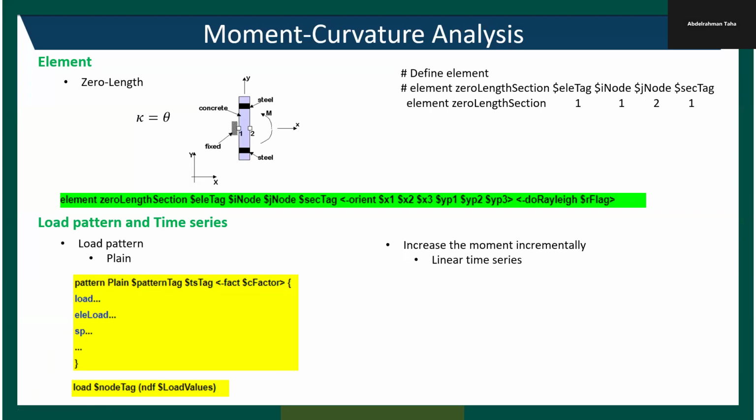Displacement control is basically you specify the displacement or deformation that you want the cross section to undergo, and then record the corresponding stress or corresponding loads to this applied displacement or deformation. So basically, we apply displacement, and we can only record the deformation of this free node.